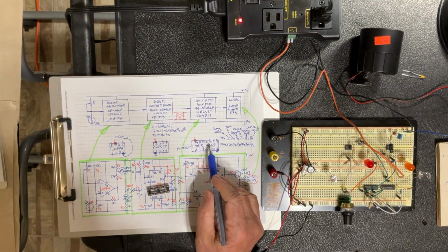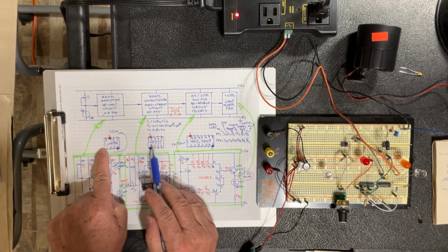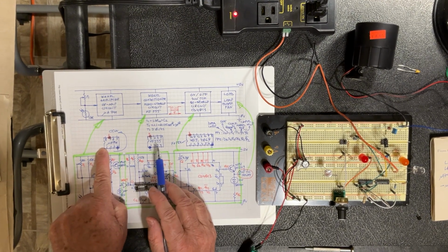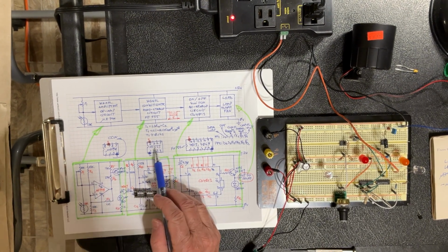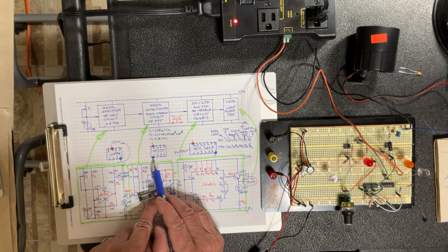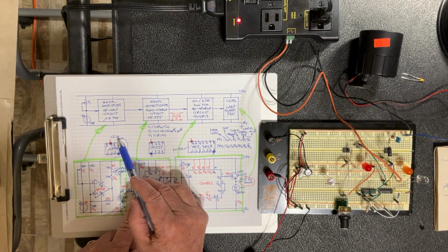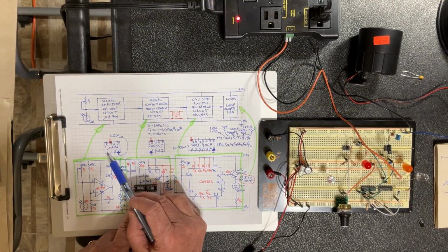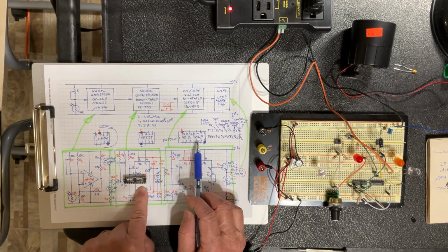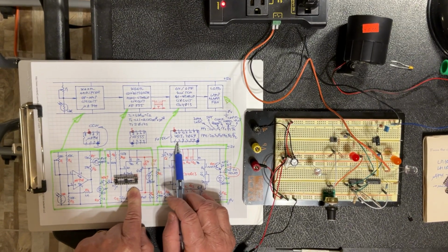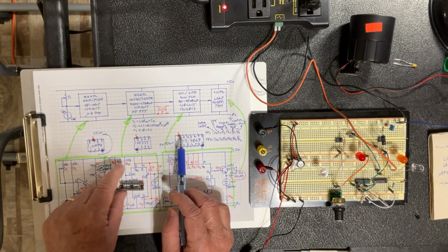This package has 14 pins. The other two packages, the signal amplifier and the signal conditioner, both have only 8 pins. But the way the pins are numbered is similar. Right below the notch, if you take a look from the top, on the bottom left, you have pin 1, and then you count the pins going counterclockwise. So pin 1 is closest to the notch, then 2, 3, 4, and you continue on the other side, 5, 6, 7, 8. For the bigger package, the 4013, you count 1 through 7, and then continue 8, 9, 10, 11, 12, 13, 14, okay?